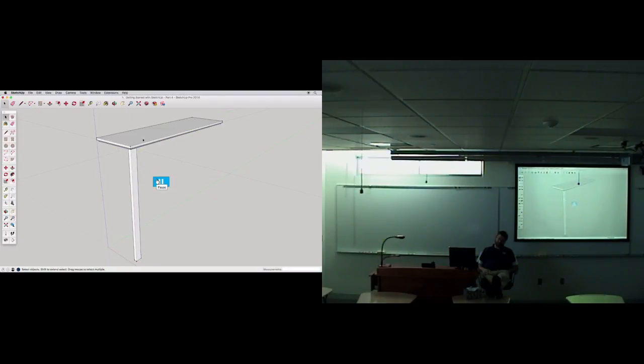While you are editing a group or component, you can draw and divide surfaces and edges, use push-pull and other tools. But once you close the group, anything you draw is outside of the group. So it's important to know when you are editing or working outside of a group or component. With that understanding, if you did modify your group in any way, undo any changes back to our original tabletop and leg. And let's copy the leg to the back side.